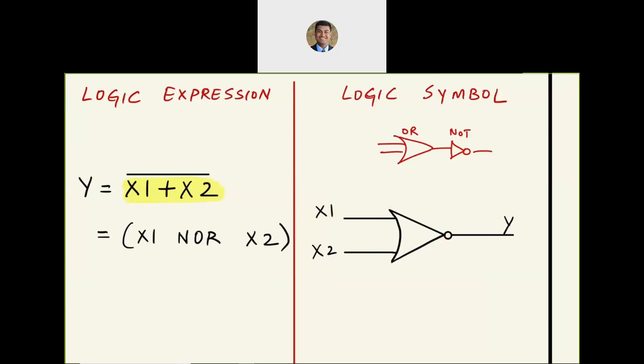And as usual, we can have more switches at the input. Now you might wonder, how many inputs can I possibly have? Well, there is a limitation on that. That limitation is called fan in limit. Remember, our voltages have a range to signify low and high states. So I will have to worry about how many inputs I can connect to the input side. I actually have to worry also about how many things I can connect to the output of any logic gate, which is called the fan out limit.